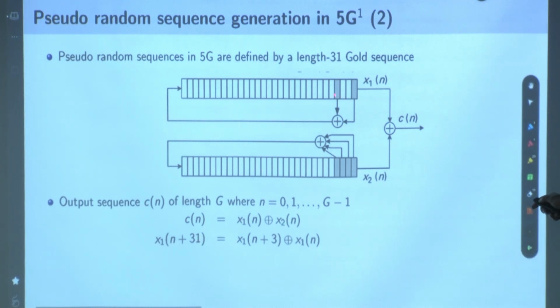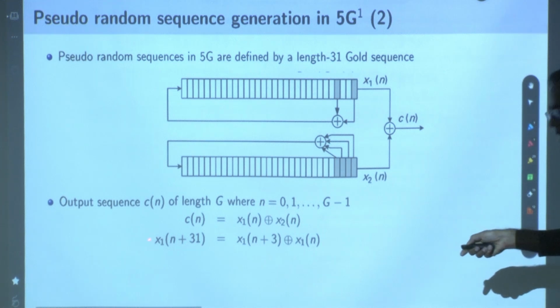You take these values, XOR them, and then write into this last register. Now you write into this, and then the whole shift register gets pushed towards the right. So you keep doing that. Any register runs on a clock; they are memory elements, and we are storing certain values in these memories. Initially we stored certain values in both these memories. Now we are regenerating new values in the memory, and how is that being done? Using this formula.